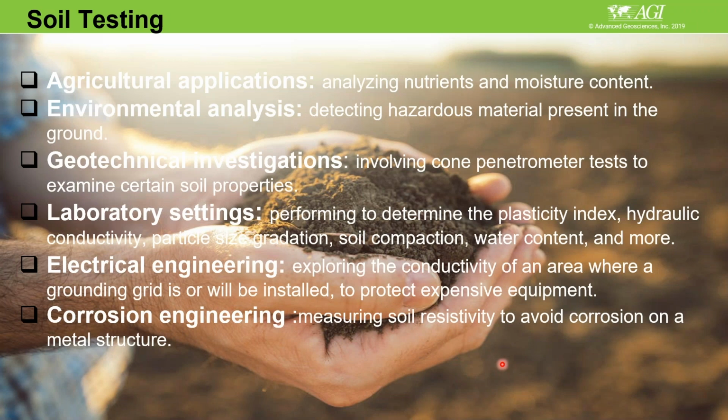All are related in some way to resistivity, because moisture content in the soil is one of the dominant factors changing resistivity values. So in agriculture, they use resistivity measurement to determine moisture content as well as salinities, for example.